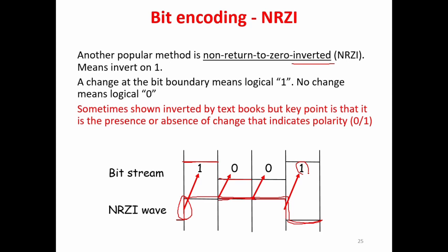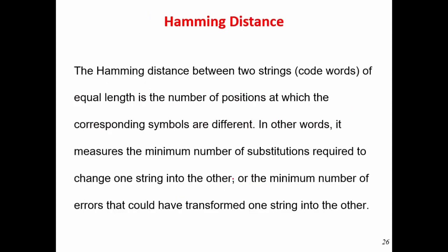So in the previous one, we needed to detect these changes rising or falling, but here simply any change results in 1. Otherwise, if there is no change, this could be 0. And this is, for instance, once we send the information using this approach, so the receiver already knows that. So this piece of information that we are sending as 1001, this is the outcome of this NRZI method. And based on that, provide the rest of the analysis.